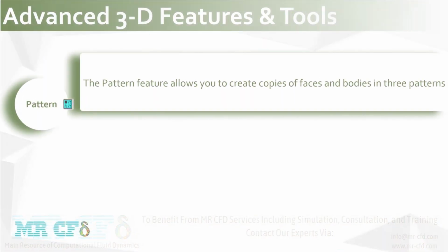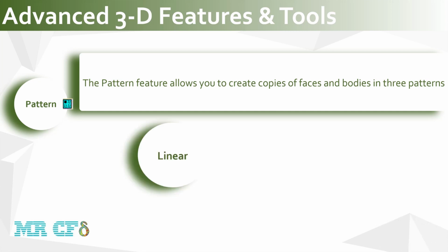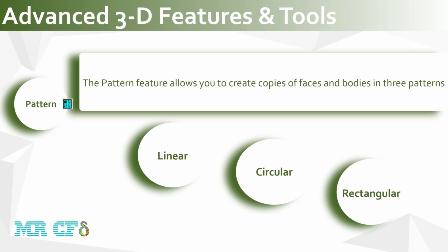The pattern feature allows you to create copies of faces and bodies in 3 patterns. Linear, a direction and offset distance is required. Circular, a rotation axis and angle are required. Rectangular, 2 sets of directions and offsets are needed.